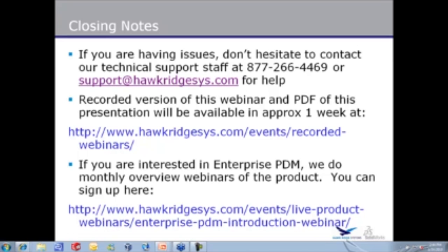Once you have Vault validation turned on, does the service restart automatically? Good question. It does not. You'll need to turn Vault validation on in the admin tool, and then you will have to restart the service manually.